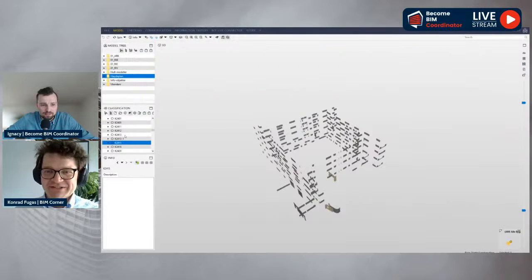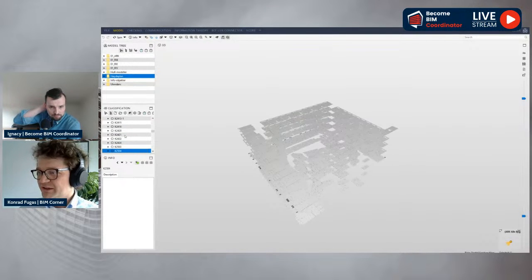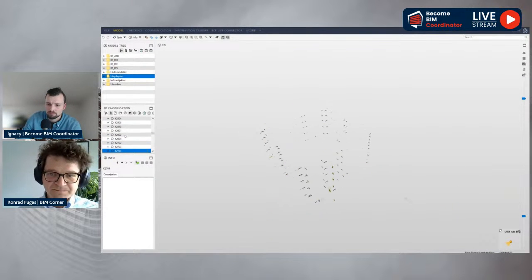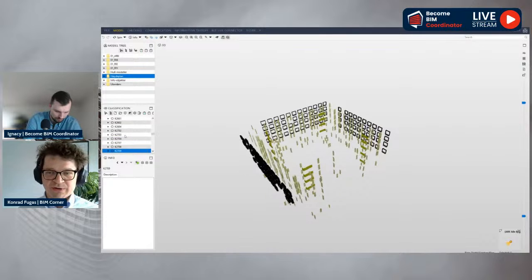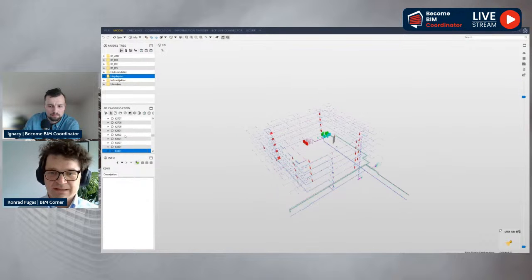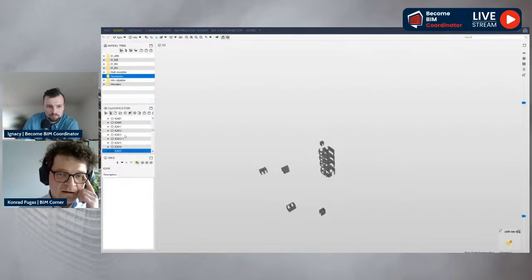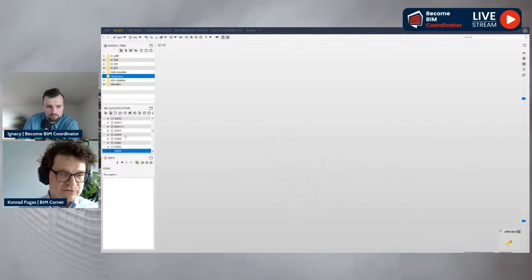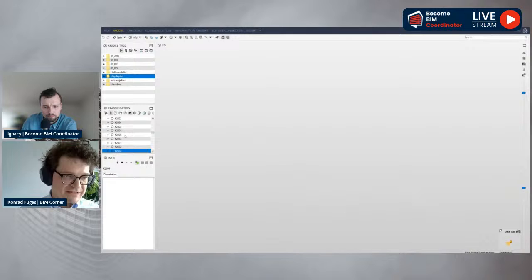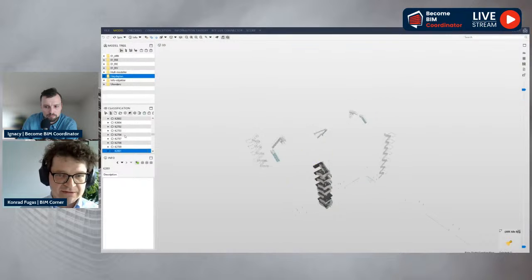Okay, the next one is just filtering after properties. You see here on the video how we structured the whole building for the properties, how we assigned them to the contract. And this helps each tender contract to filter out models for their contract and check for feasibility as well. Received very fast and pretty good quantity estimations. And what else? A contractor can create an ITO filter using this classification code, those classifications we created in Solibri, to further narrow down the results.